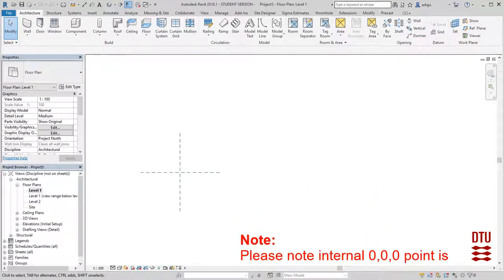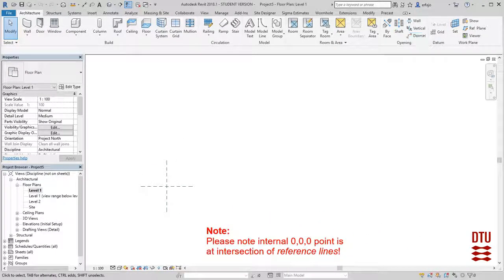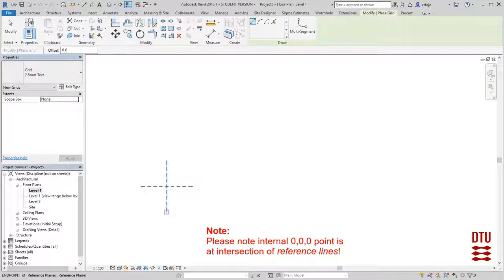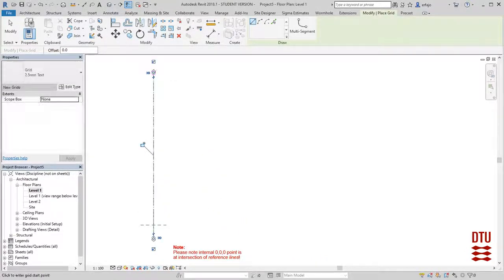This time, this is also the 0.0 in this project. And we must be sure that this position can be found anytime we need it. So this is the 0.0, and you should put in a cross where you have A1 as the grid, marking that position.